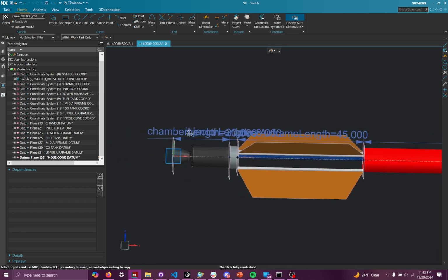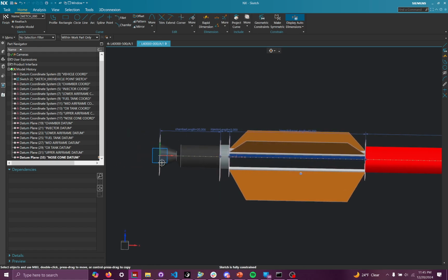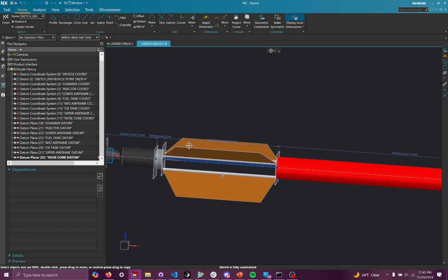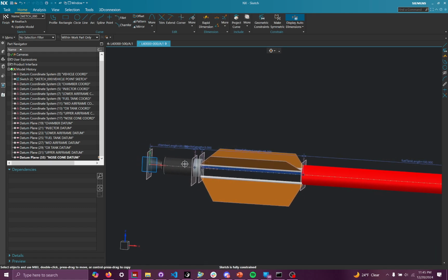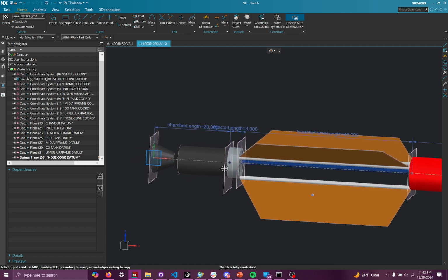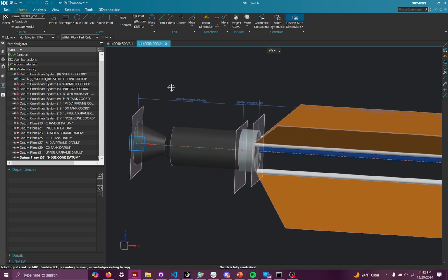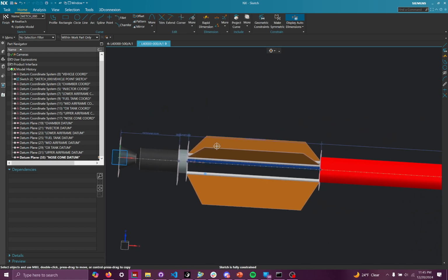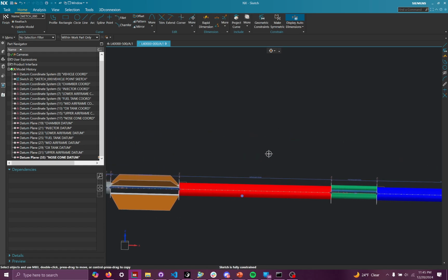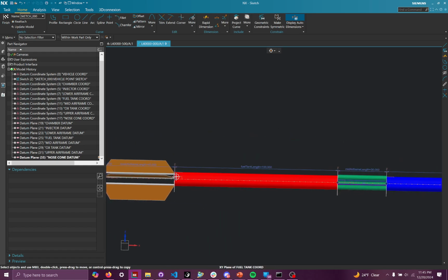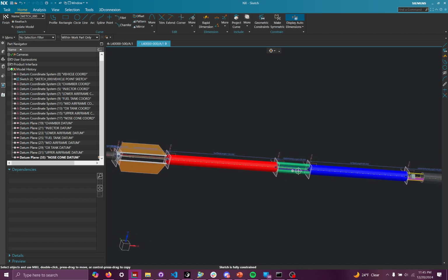So this vehicle point sketch is defining the lengths of the different subsystems making up the rocket, and we actually define the planes, the datums, based on locations of points within this sketch. So I can change any of these named dimensions and have that change the relative positions of these datums to each other. So let's do a quick demo.